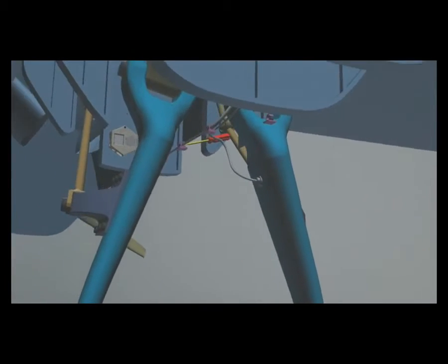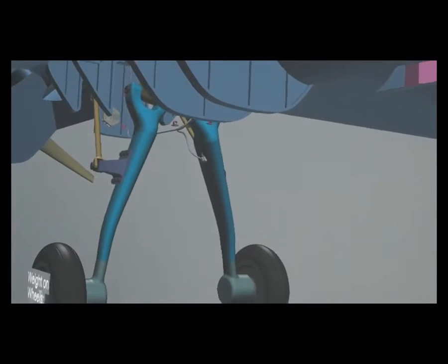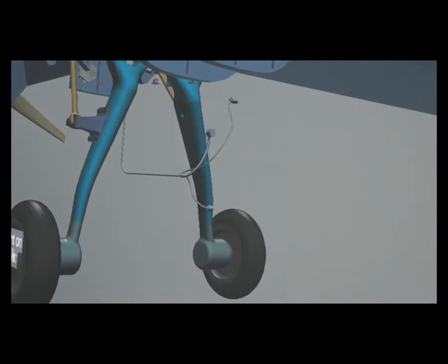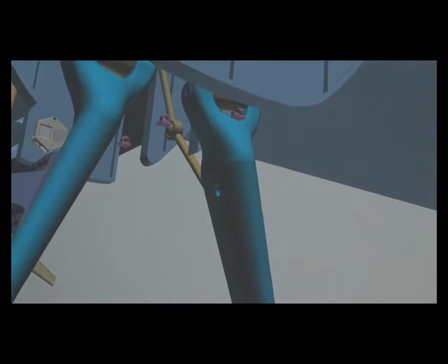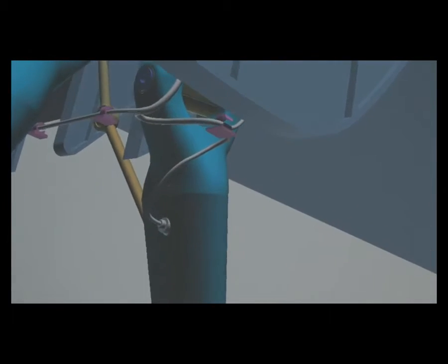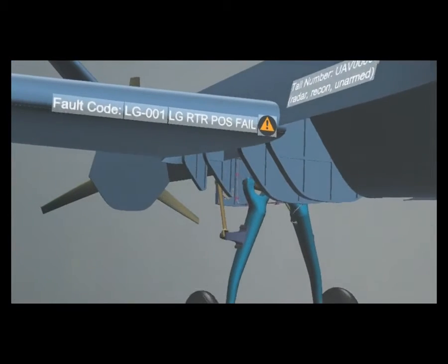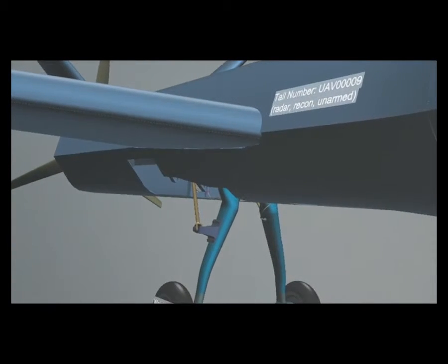Aircraft procedure next. Release wire harness assembly from clip locks one at a time, while maintaining a secure handhold on the wire harness. Aircraft procedure next. Place removed wire harness assembly in safe area. Visually inspect clip locks for damage and replace as necessary. Aircraft procedure next. Remove new harness from packaging and install with additional clip. Connect harness ends using torque wrench to 10 Nm torque. Aircraft procedure next. Procedure to remove landing gear wire harness completed June 2, 2017.